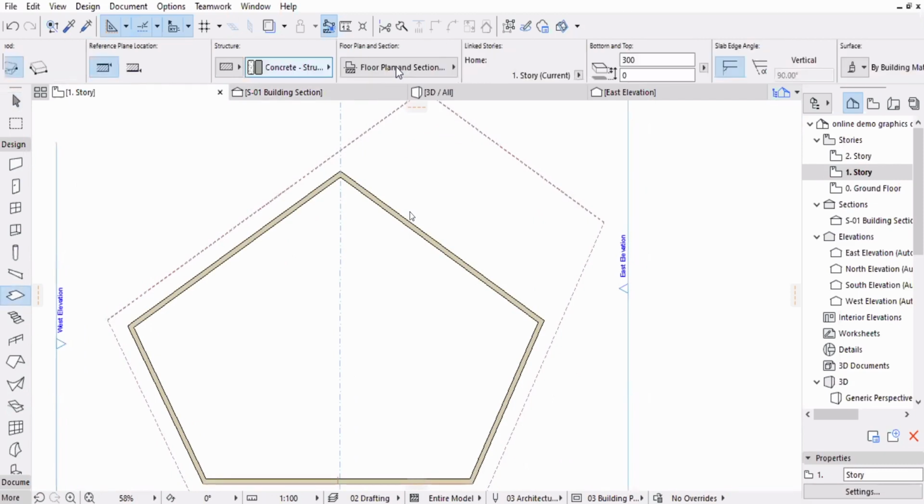And what this icon says is, you have to draw the slab, and this height is always taken to the top. So if it's 3 meters, it's always taken to the top of this, fine? And the thickness goes down, okay? Unlike for walls and all, when we draw walls, what happens?